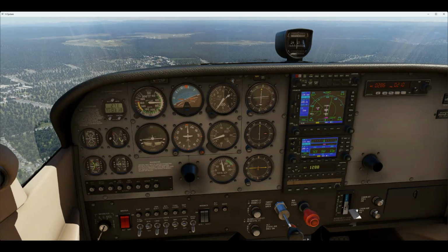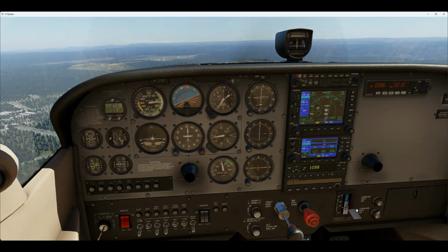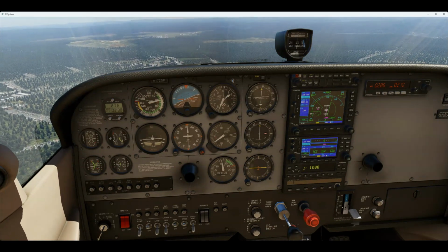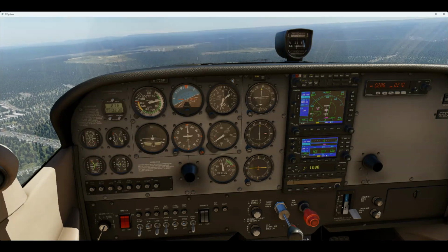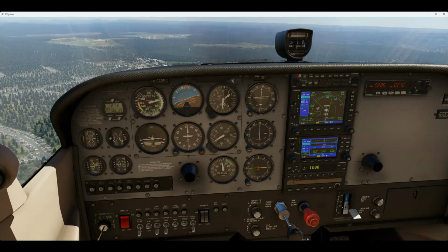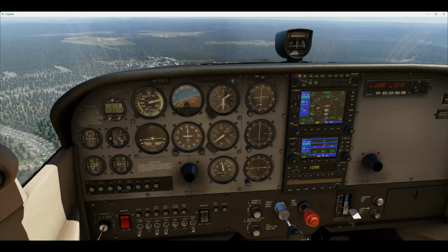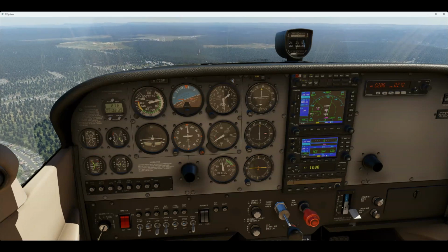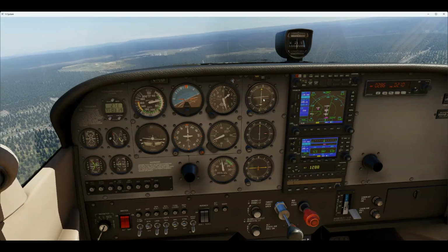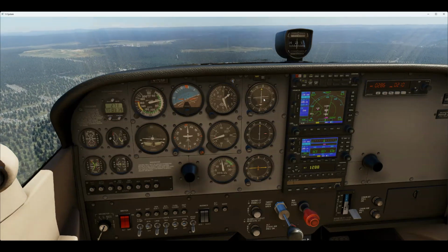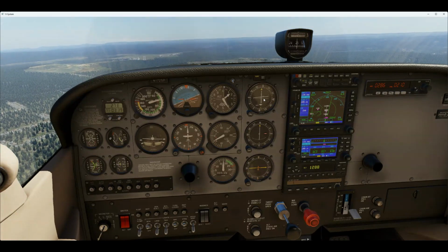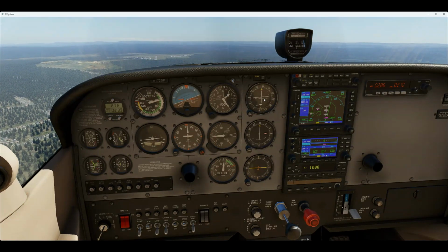Okay, we still want to ascend a little bit, but again, we want to get that glide slope back on, going down. So at the moment it's telling me to keep flying up, so I'll keep flying up. And we're back on vertical guidance almost. On horizontal we're good, so the left-right needle's almost in the middle. It's telling me slightly fly left command. You can see I only do a couple of degrees at any one time. It's telling me fly up, so a little bit more power to fly up a little bit.